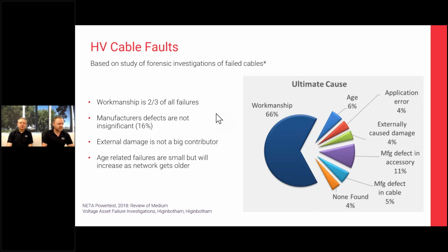We'll look into that. So let's go back to what causes HV faults. Workmanship, unfortunately, is a significant factor. When you're looking at that workmanship, the early life failures are something to consider. So this isn't just technology that you should be doing on the aging assets. It's really for that beginning of life asset as well.